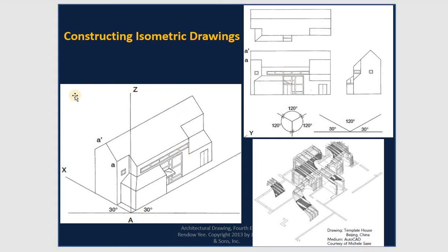Now, the homework is you need to create an isometric 30 degree, 30 degree. And you need to create exactly the same right here. So you look at the face right here, exactly this one. And the face right here is on this side, in this side. To look at this one. So 30 degree. It's not hard. You just create the first line for the Z. That means the height of the building first, and you create 30 degrees right here, 30 degrees right here. After that, you start on the projections.